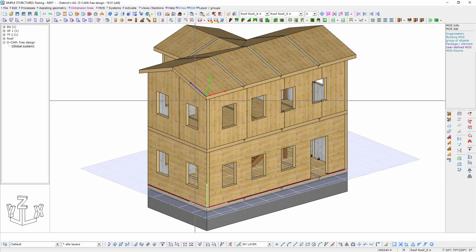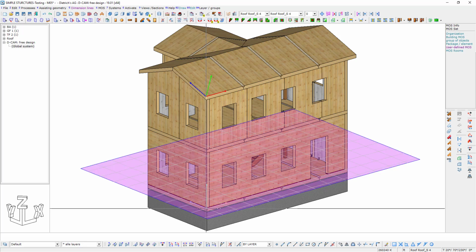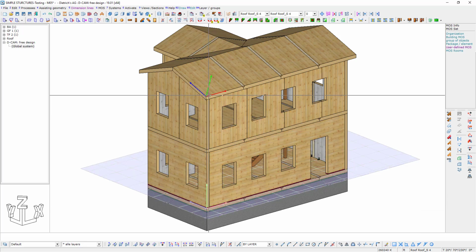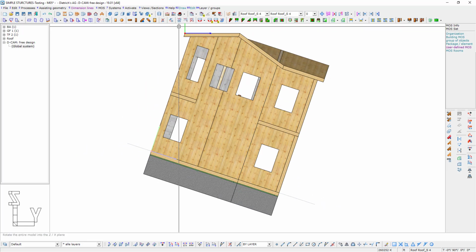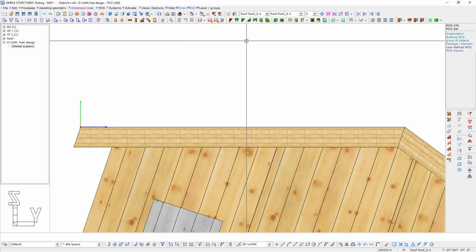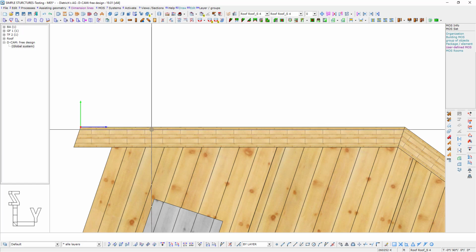When I do that, you'll see that my coordinates come up for that roof system. You'll notice the X, Y, and Z axis here again, but this time they're at an oblique angle when compared to the global coordinate. All right, completely different coordinate system. Now what's cool about this is I'm going to go into a side view of this. Now I'm on this coordinate system, so if I select side view, there it is, and it gives me a side view perpendicular to that plane.